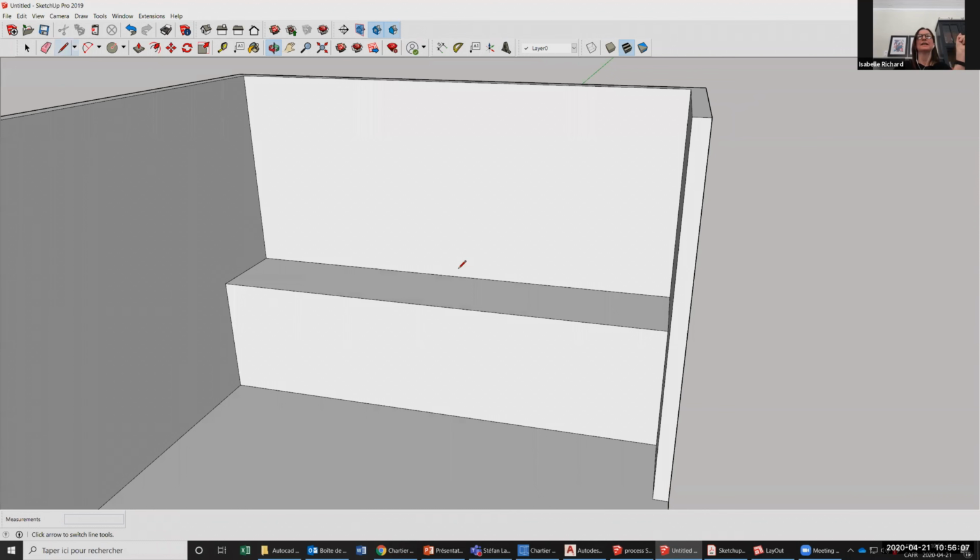So what I'll do is, remember the main points that you know of on your drawing are the end points and the midpoint. So I'll just start from the midpoint and I'll go this way, force my direction, 15 inches on the right side. So I will create another segment that ends 15 inches from the middle, and then do another drawing.